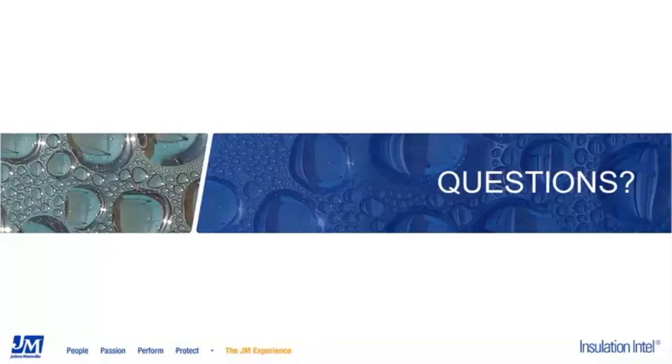It might be a good place to put an insulation expansion contraction joint. It would really depend upon the style of pipe expansion contraction joint. So I think that's probably more a case of talk to us, we'll work with you and your insulation contractor, and we can come up with an appropriate way. But the most important thing is to maintain your vapor retarder continuity across that location.